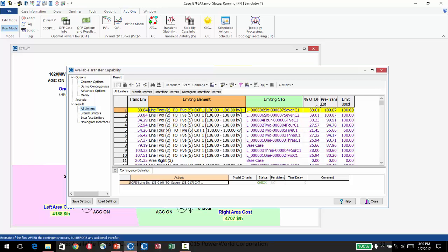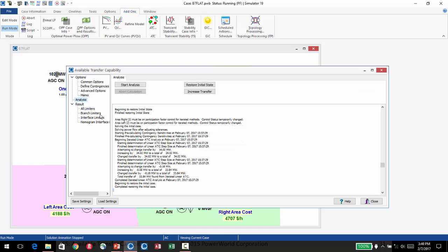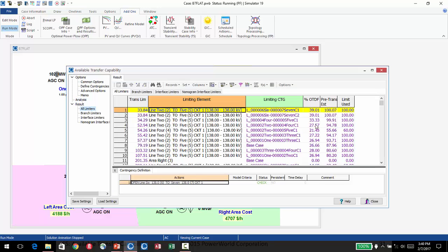So you can't directly examine these numbers and then dump them into the equation on that slide that explained what the transfer limit was. You can dump them in from a starting point of that step that it took, that initial step of 34.02 megawatts. All these other values are calculated off of the last solve point, which was right here.